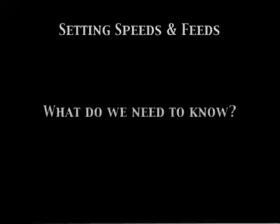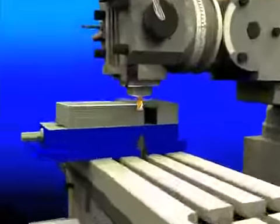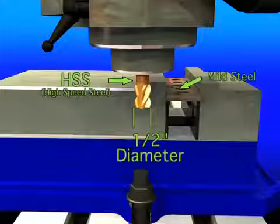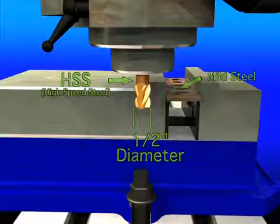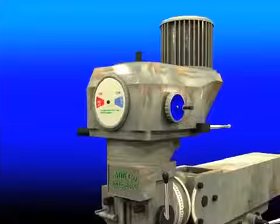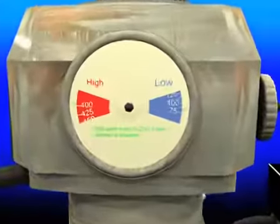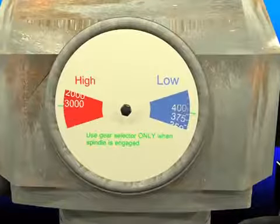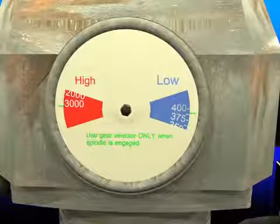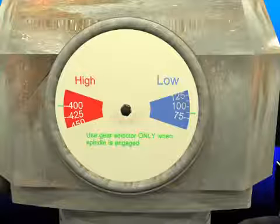What do we need to know in order to set the RPM? The diameter of the cutter, the material of the cutter, and the workpiece material. What is the average RPM range of a standard milling machine? In high gear, the maximum RPM is around 3,000, and in low gear, about 400. The spindle can rotate as slow as 75 RPMs in low gear, and in high gear, about 400.